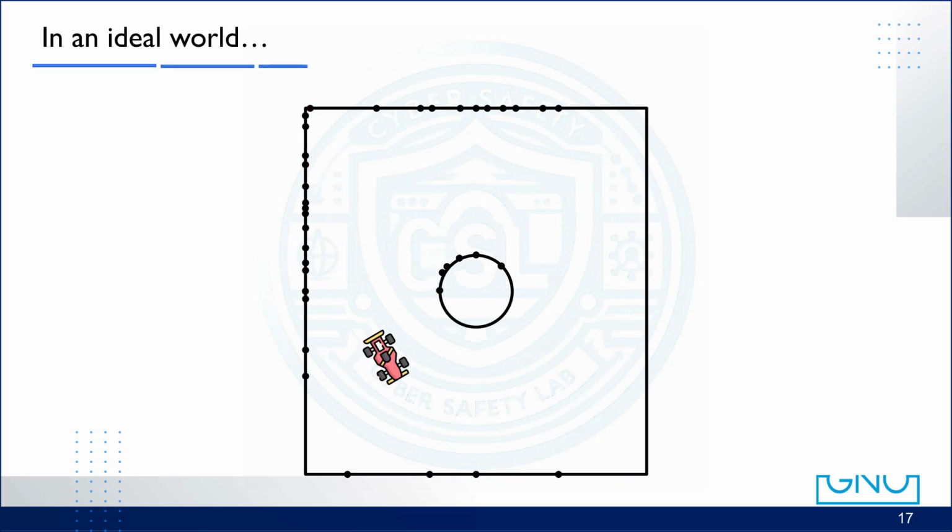As the robot continues moving, perfect odometry gives us an accurate trajectory. Each new pose becomes another opportunity to place the next scan in exactly the right spot. As scans accumulate at each pose, they align flawlessly, forming a complete and perfectly consistent map. Under the assumption of zero error, SLAM becomes nothing more than stacking each scan in the right place.